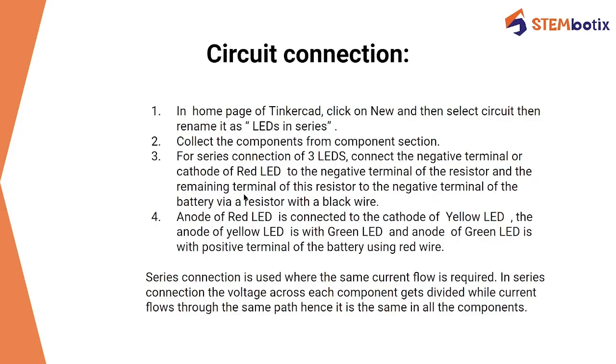Now these are the circuit connection steps when you are making the circuit in Tinkercad. On the homepage of Tinkercad, after clicking onto Tinkercad, its basic interface will appear. Then click on the create button and then circuit. Then rename your circuit as LEDs in series. Collect all the components from the component section.